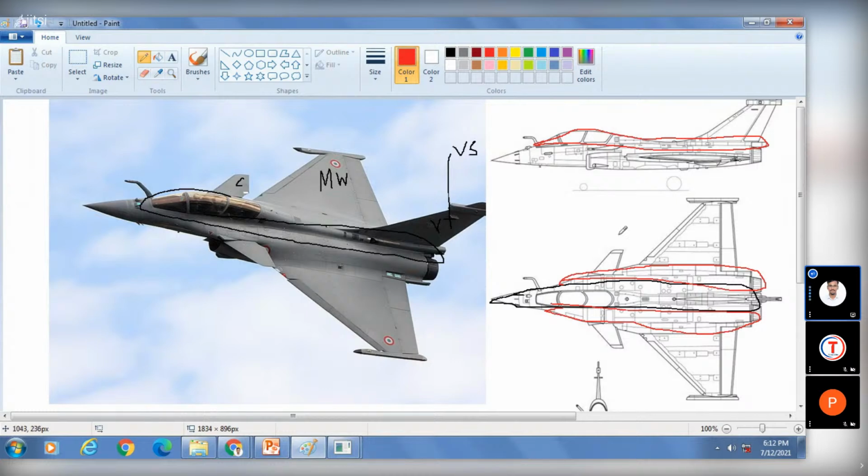And here no need to split our wing section, because this wing is like completely delta wing, like this. Okay, so no need to split, we'll go according to that. Okay, like this we can design delta wing. Yeah, and after that we have our canard wing. So with the help of wing section we can complete this part, right? So now we'll go to main wing.